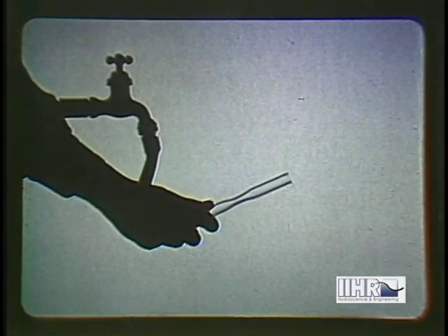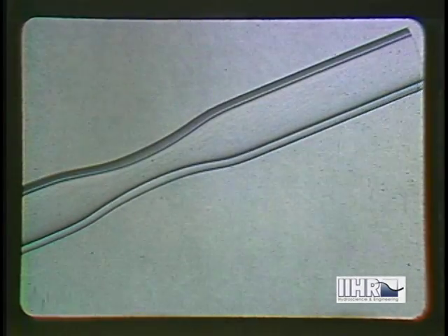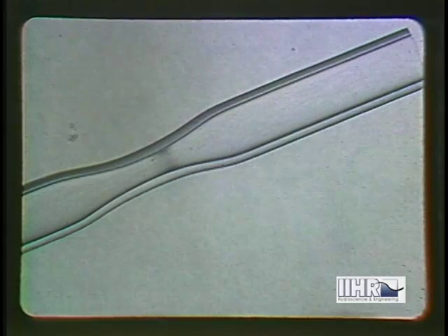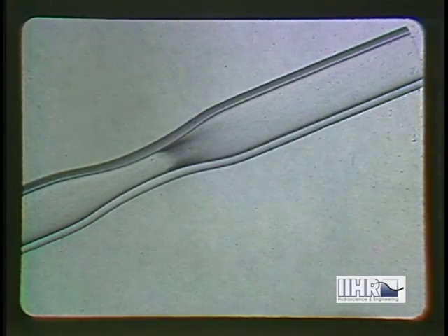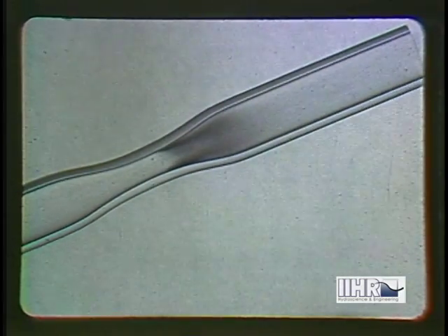Another phenomenon that limits use of the pressure-velocity relationship is called cavitation. As Osborne Reynolds demonstrated with a glass Venturi tube nearly a century ago, the velocity can be increased to the point that the pressure drops locally to the vapor pressure. The liquid then begins to boil at normal temperature.